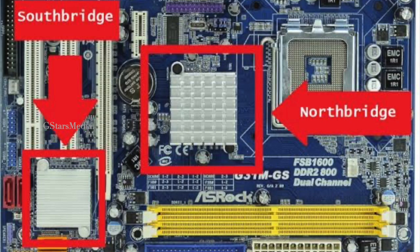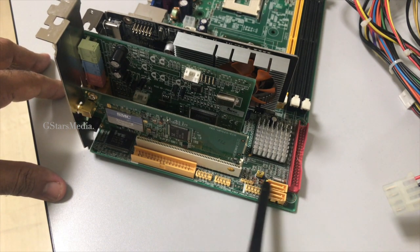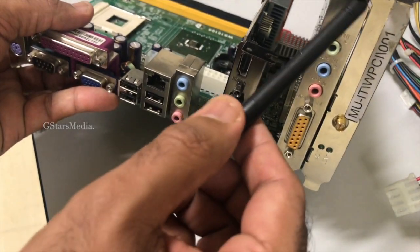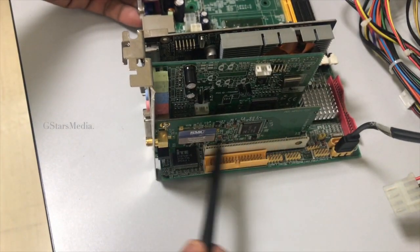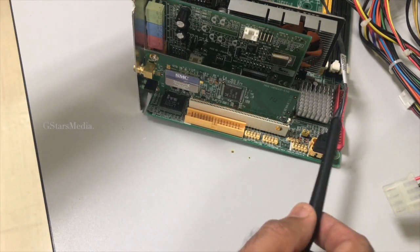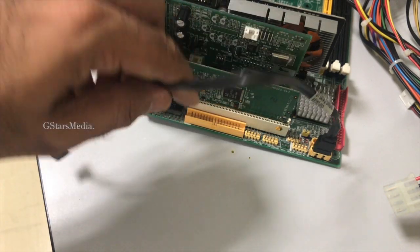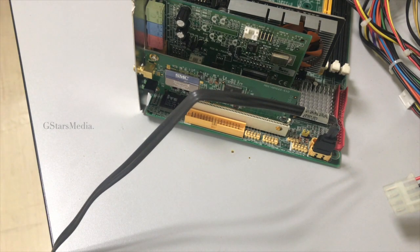South Bridge. The South Bridge, also known as the I/O Controller Hub (ICH), was responsible for managing lower speed peripherals and connections such as USB ports, SATA ports for storage devices, audio inputs/outputs, PCI slots, and more. It handled communication with slower devices and provided support for various I/O functions, including data storage and connectivity. Functions of the South Bridge were generally less time sensitive and lower bandwidth compared to those of the North Bridge.